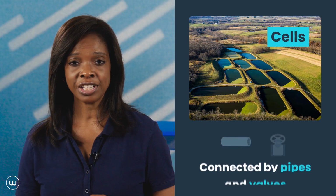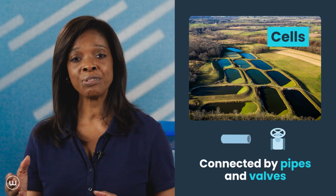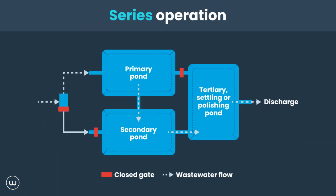Modern wastewater pond systems typically consist of 3 or more separate ponds, often referred to as cells, which are connected by pipes and valves. When arranged in series, raw wastewater flows through the ponds in order. The first pond acts much like a primary clarifier, while the last pond functions as a tertiary or polishing pond. This layout allows each pond to perform a distinct step in the treatment process.